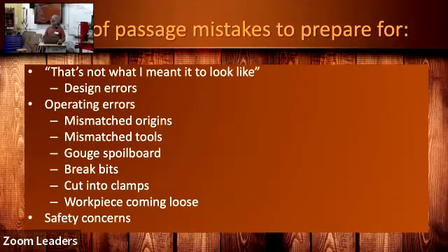You can break bits. I haven't done it yet, but Dave has broken at least 3 since I've, all right, never mind. You can cut into clamps. We showed you the picture of that. Bits break from too fast a feed rate for too small a bit, or putting the bit where it has no business being, hitting something, like clamps. Starting up too fast is another way of busting a bit. If you're dealing with a 16th inch bit and you're going to go at 40 inches a minute, if you're going to hit something solid, it's going to break.